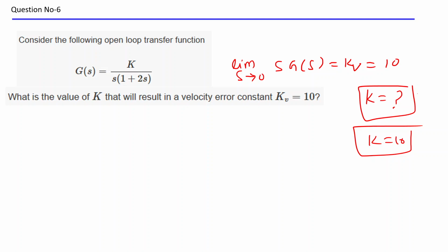The main purpose is that you have to familiarize yourself with MATLAB: how in MATLAB you do a Bode plot, how you sweep, how much gain is required, how much phase margin is required, how much gain you have to adjust to make the system stable or to arrive at a specific requirement of the system. You have to use MATLAB frequently to become acquainted with the compensator system.